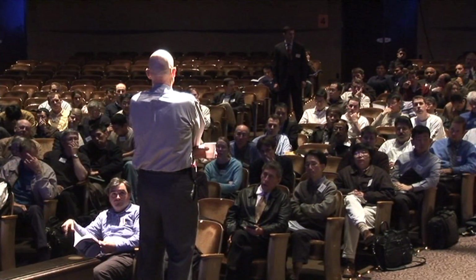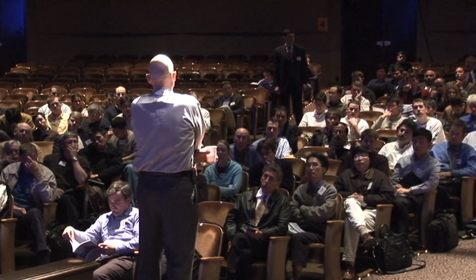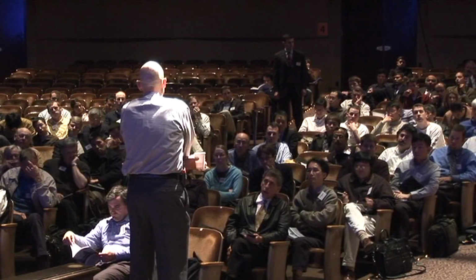Okay. For that chord rotation model. Not the case for steel, though. Pardon? It's not the case for steel. No, the reason is that the capacities given for the chord rotation model in ASCE 41 are plastic end rotations directly. And it turns out they're the same as plastic hinge rotations. In fact, in the FEMA beam model in Perform, it actually converts to a plastic hinge model.